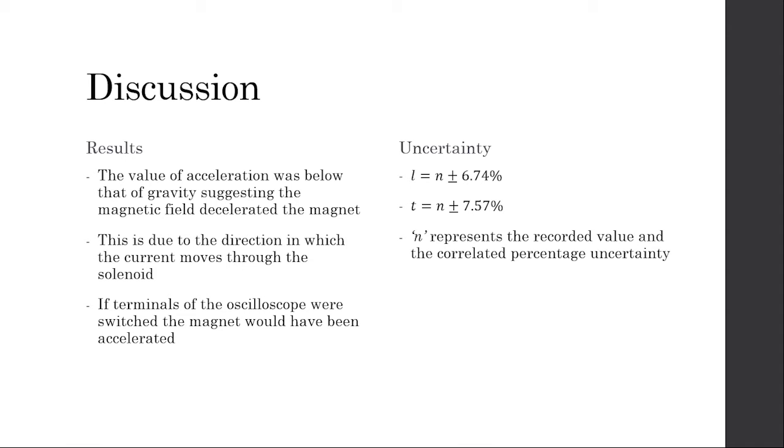However, the sensor could be better as it is limited by what it can measure. High amplitudes can peak outside the measurable range of the oscilloscope, giving results that cannot be properly analyzed. Another shortcoming of the oscilloscope is that there is no storage memory available. Because of this, comparisons between data cannot be drawn between tests on this device, leaving potential error when transferring data across to a different medium.